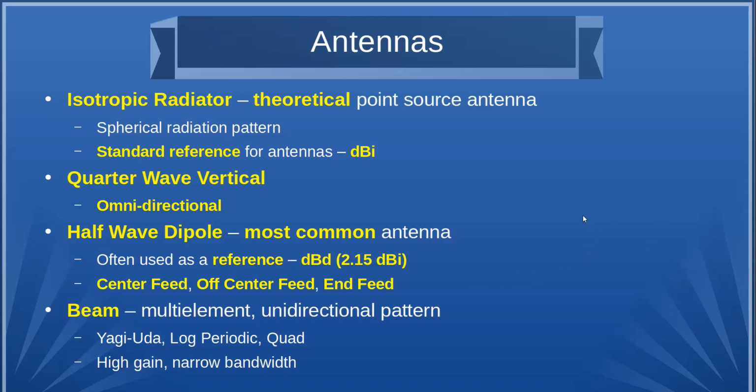I have a center fed fan dipole right now that definitely is more than 6 dB greater than my vertical. In some directions. Yeah, but it seems to be all directions. Remember, I'm probably closer to a 90-degree inverted V. So it's fairly omnidirectional. It's slightly oblong, and because it's pointed a little bit east of north, I get sort of over the pole stuff, and Europe is a piece of cake.